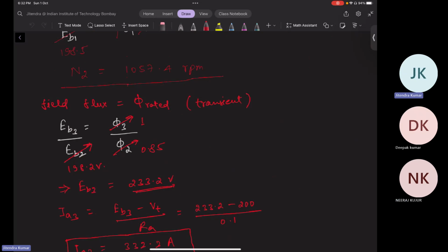That's why I mentioned the electrical time constant. So when you are changing, it will reduce according to the electrical time constant, that is your L by R, inductance of the circuit and resistance of the circuit, isn't it? Yes. But your mechanical time constant is way higher than this.